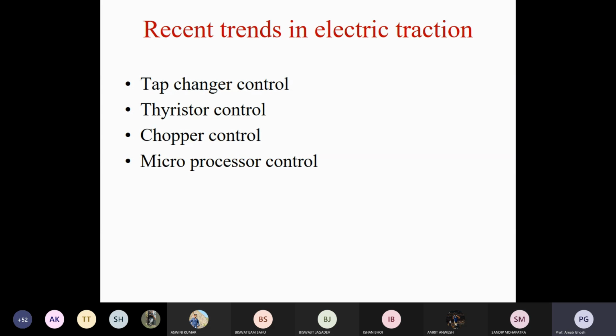For their application and designing purpose, the code specifies what the gauge of the wire will be, what type of insulation needs to be used, and what the testing rating will be when you are testing your motor. Vacuum testing is there for insulation. Different testing labs are also inside your workshop, so that is also maintained.